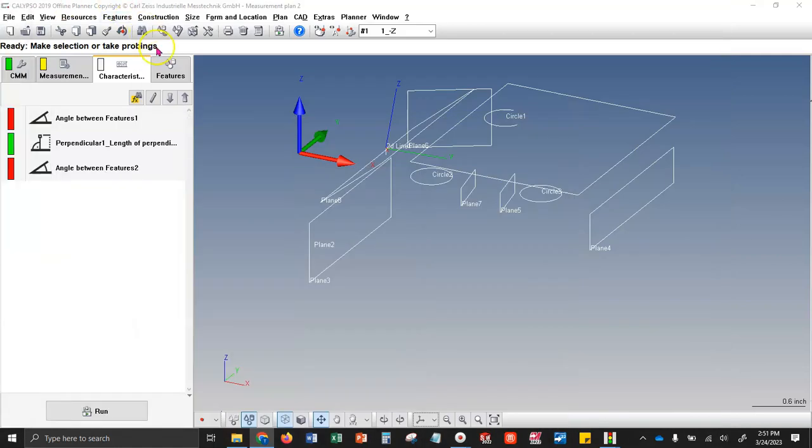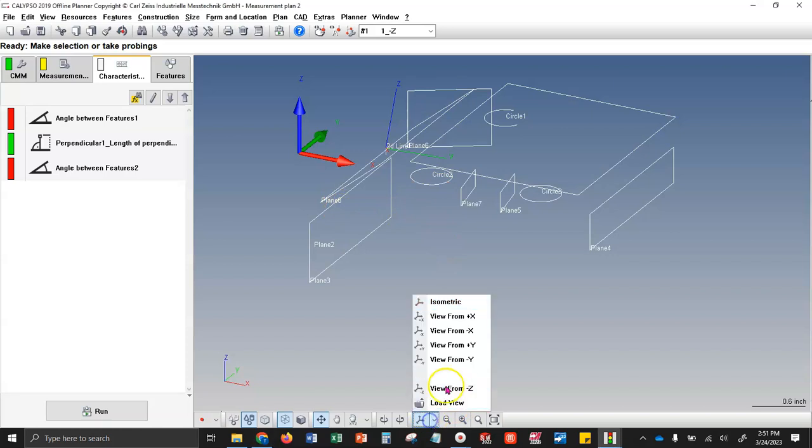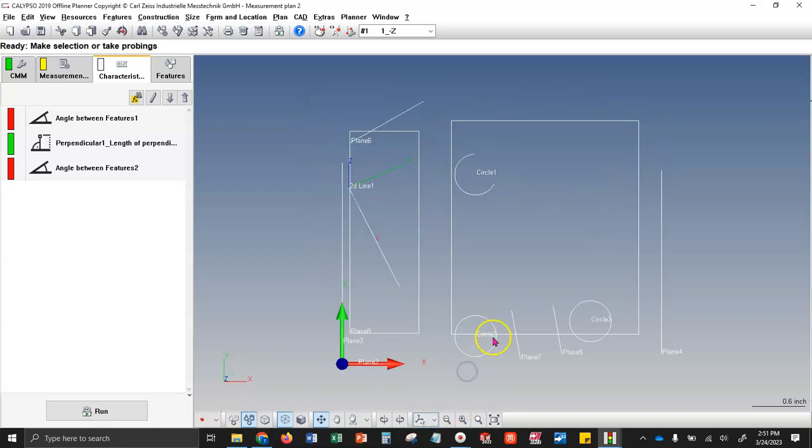We have to use a polar caliper distance because we're not going straight along the x, and we're not going straight along the y. If we were going distance from here to here, that would be regular caliper distance. If it was distance from here up to here, that would also be regular caliper distance. This would be y, that would be x, of course. When we do polar, we're taking the shortest path on an angle from hole to hole.